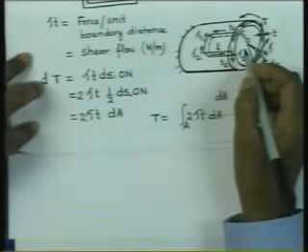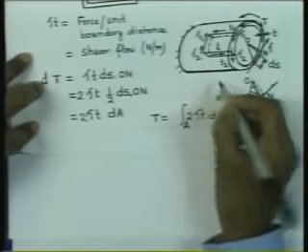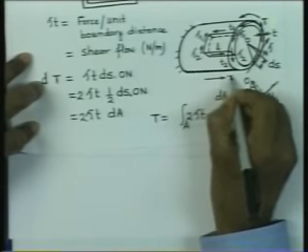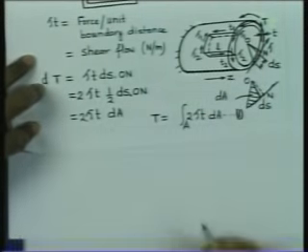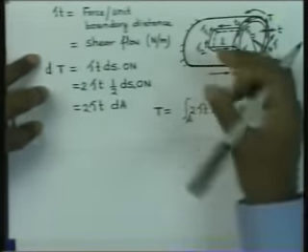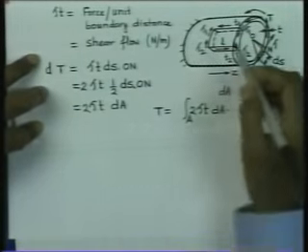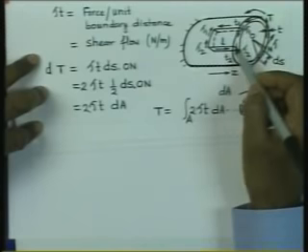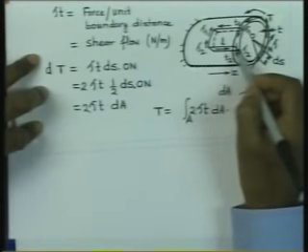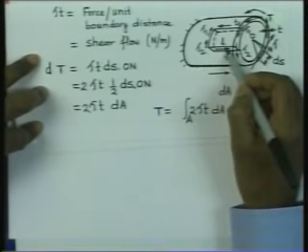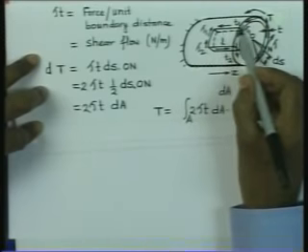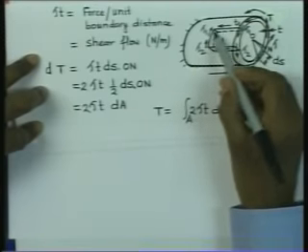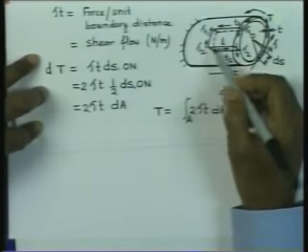If you would like to consider that axial direction is equal to Z, this is our Z direction, then take the element out and think of forces acting on this boundary which are of intensity tau 1 there, tau 2 there, and on this face we have uniform stress of magnitude tau 2, on this face it is uniform stress of magnitude tau 1, and here again we have tau 1 here, tau 2 there.